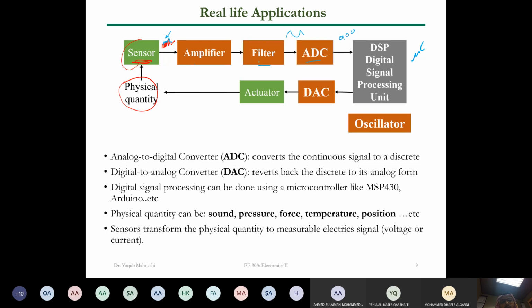So we have an amplifier, we have filters, we have ADCs, and we can do the same when we go back to the speaker. The actuator here is your speaker. So this is the microphone, and now this is your speaker. Going that route from here to there, you need these kinds of blocks, and then you also need to go back by converting the digital signal to an analog signal and send it to the speaker.